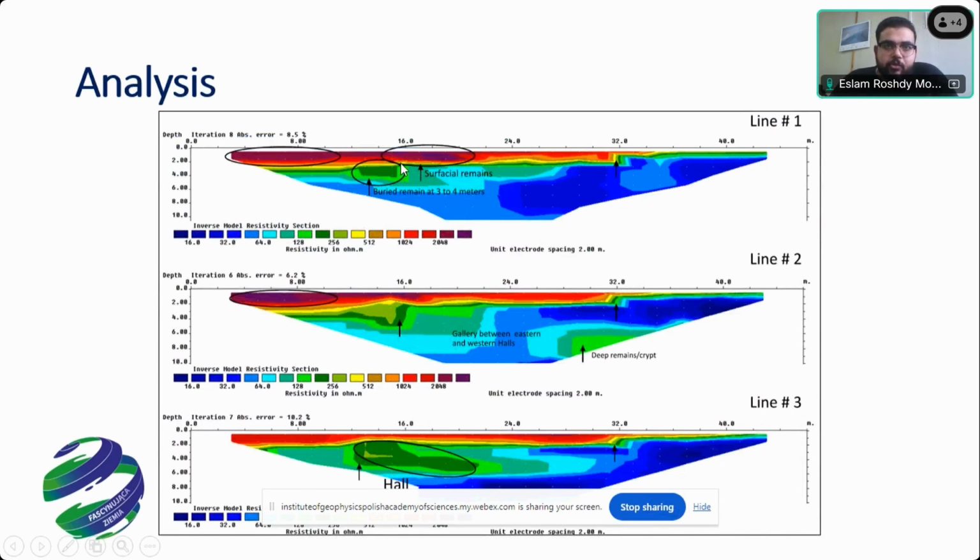and by analyzing every line, we noticed the inverted ERT profiles show very high resistivity anomalies, more than 900 ohm-meters. Red colors mean resistivity of 1024, which is a very high anomaly, and these are seen on different profiles.